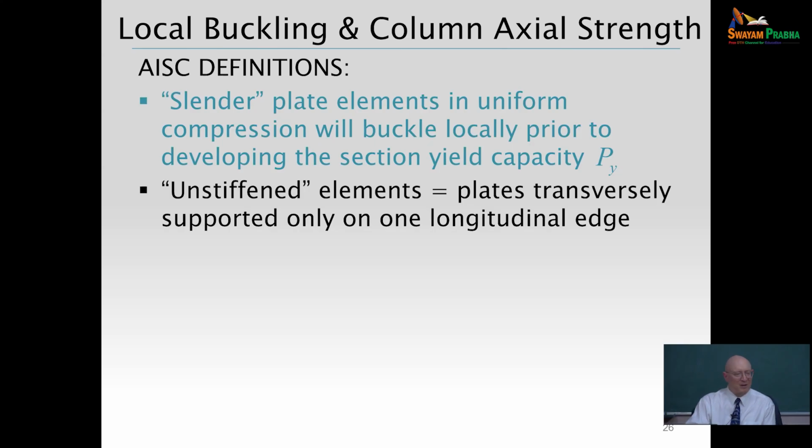Okay, so then the other definitions I was thinking about here. If you have something like a web of an I section, where you could say that web plate is supported by the flanges on each of its longitudinal edges, AISC calls that a stiffened element. Okay, is that what you would call it in the Indian Standard? Yeah.